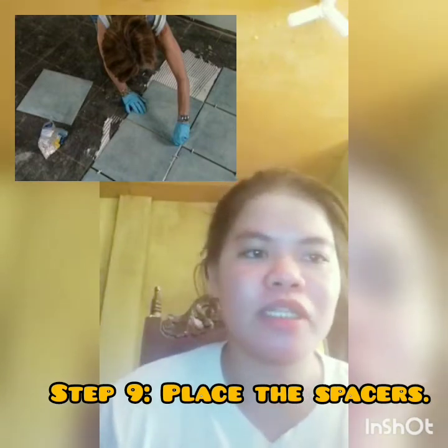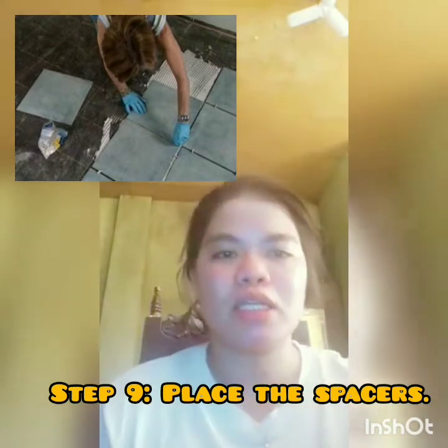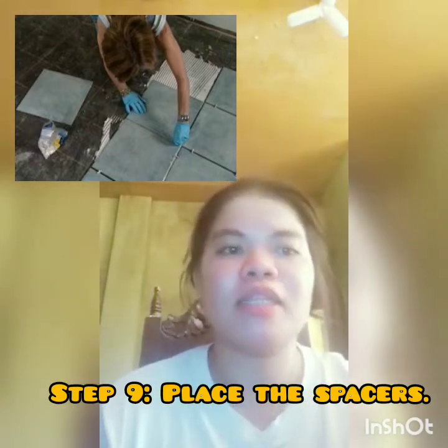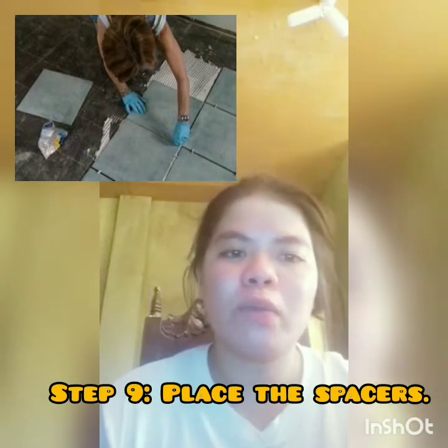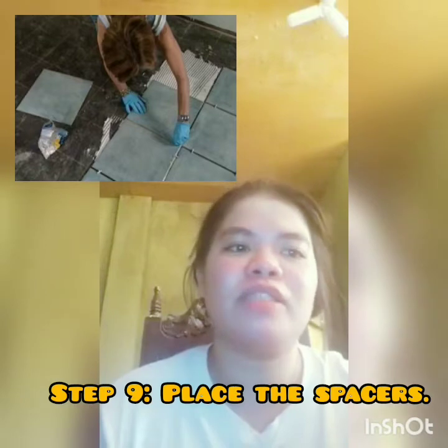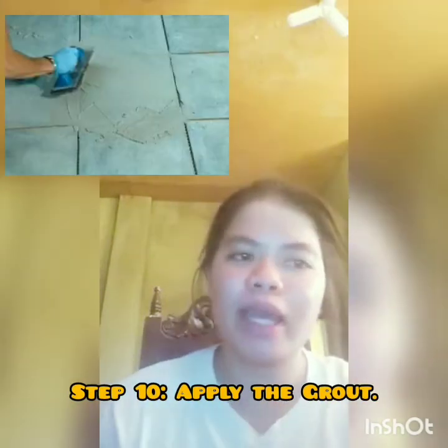Continue the process using the chalk line as a guide and placing spacers between each tile to ensure uniform distance between the tiles. When all the tile work is complete, allow the tiles to dry in place for several days before grouting. Step 10. Apply the grout.